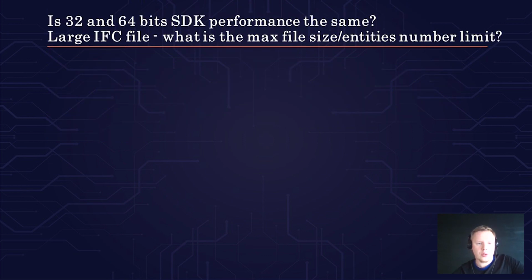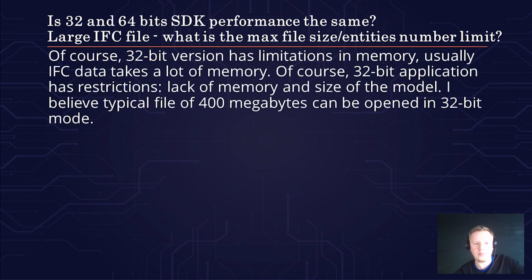Do 32 and 64-bit SDK work with the same performance? In case of large IFC files, what is the max file size, number of entities limit? Of course, the 32-bit version has limitations in memory.